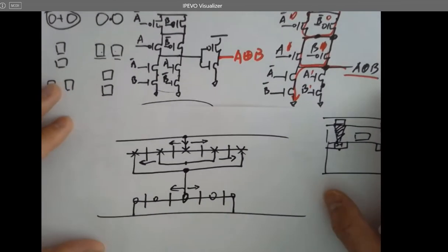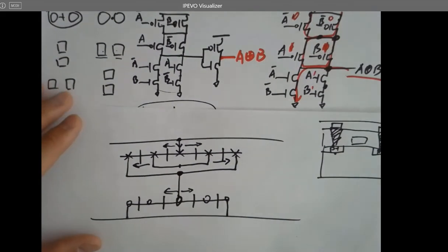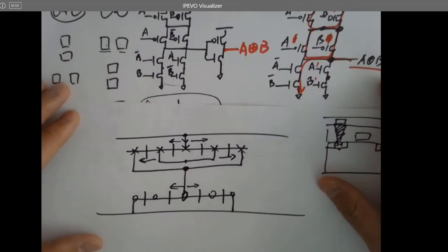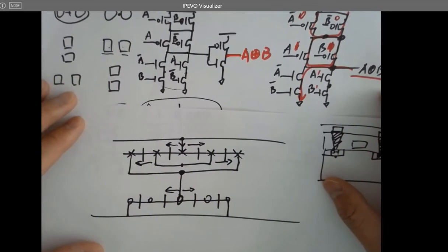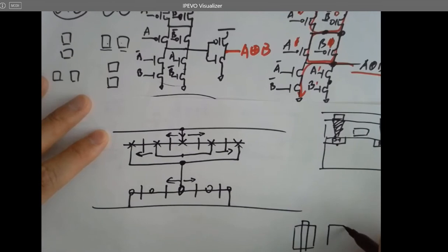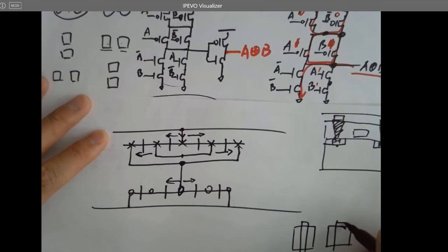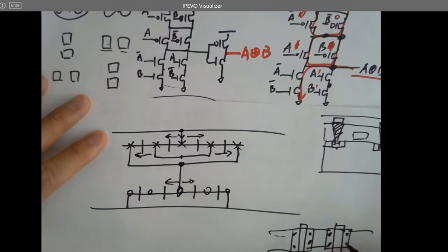In some designs, if you're not using the gate to turn on and off, so it's always on, then in these cases you don't even need the gate to be there. It's going to have the same effect. Which means if you have a circuit like this, 2 NMOSes in series, these are the vias, and you have a metal to connect these 2 together, and here's another metal one to the other circuits. That's in, that's out.